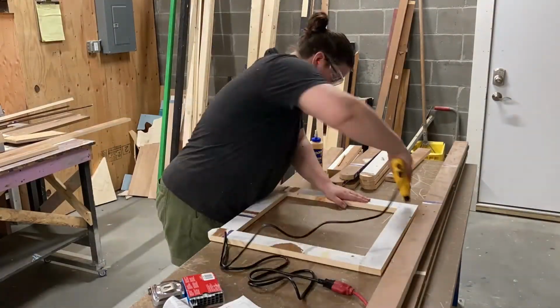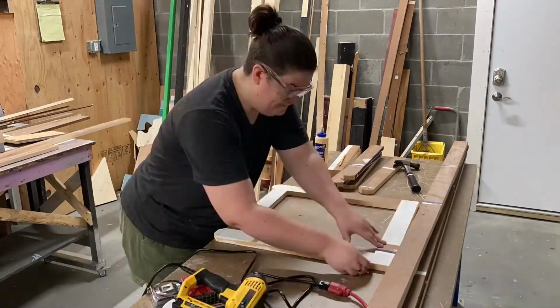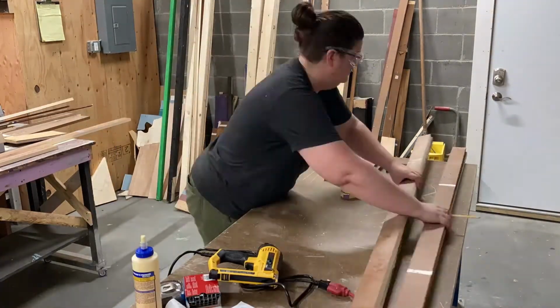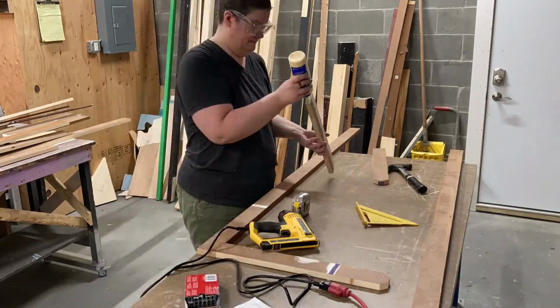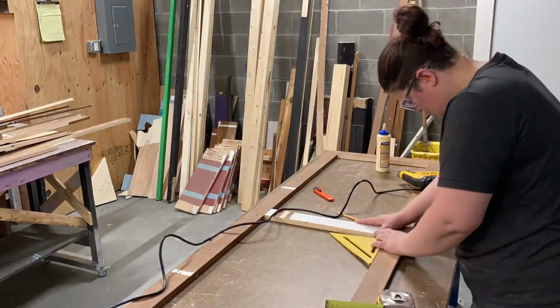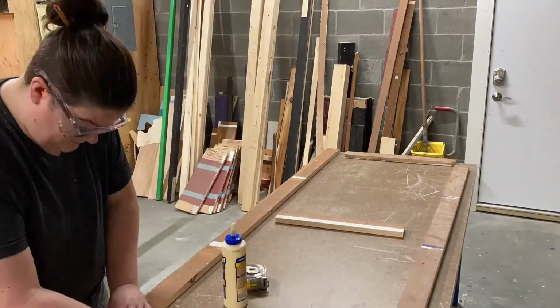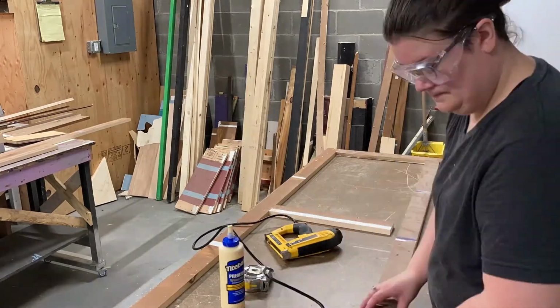One parallel unit requires 3 of these narrow frames. If we were preparing a full stage deck for a set, there might be upwards of 60 platforms requiring around 180 identical frames. In such a scenario, a carpenter might use wooden blocks to set a jig or template on their work table, eliminating repeated measurement for alignment and keeping the work consistently square.